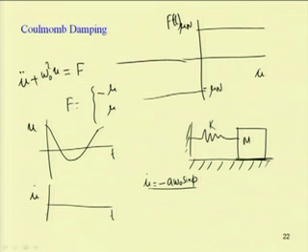So, this is u dot, that is your minus a omega 0 sin phi. Up to pi, from 0 to pi, this becomes negative. So, this is u dot less than 0, and this is u dot greater than 0. So, if u dot greater than 0, this force will be equal to minus mu, and if it is less than 0, one can see the opposite.